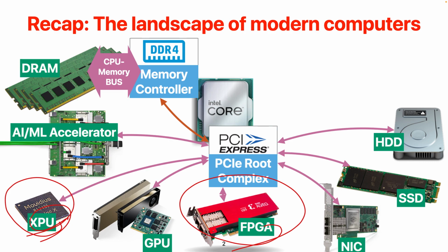However, there's nothing that is good in all aspects. One drawback that I can see from FPGA is the performance limitation, right? In a lot of cases, because FPGAs are not designed to be application specific in general, they are pretty much limited by the speed of SRAM.